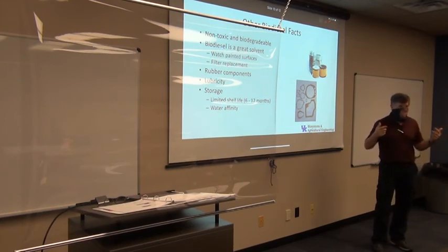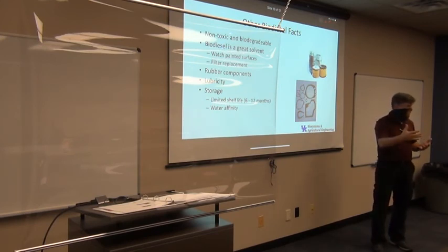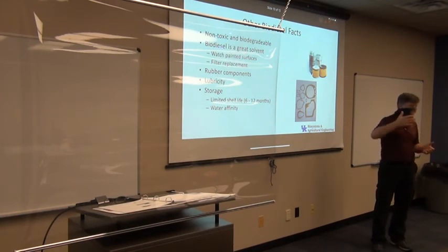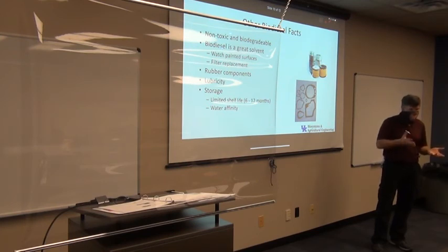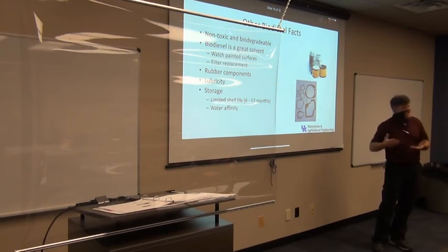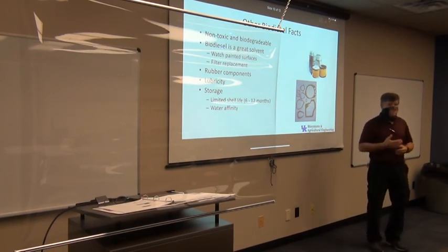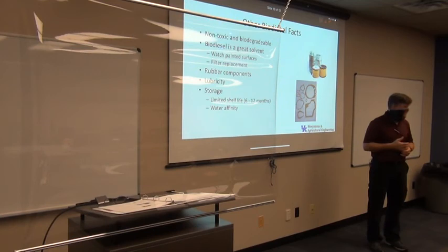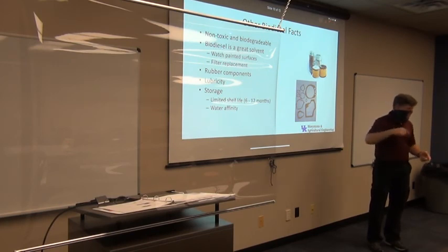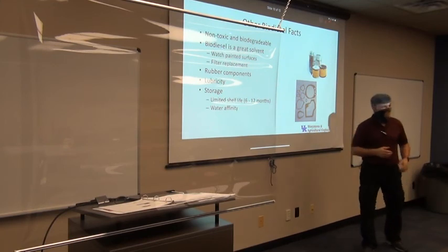So when we talk about the fuel oxygenating, or becoming oxygenated and no good, gasoline, if you store it too long, just won't work anymore. Part of that is because of the water that it pulls in, that it reacts slowly, same kind of reaction as the combustion reaction, but that oxygen is breaking down the fuel, and it's no longer a fuel molecule. So we really have to watch water, and you have to think about the shelf life of fuels, how long you leave fuels. That can become a problem. In our lab down there, a lot of our lab engines we use a couple times a year, so we have to always be flushing them out and putting fresh fuel in them so they work well.